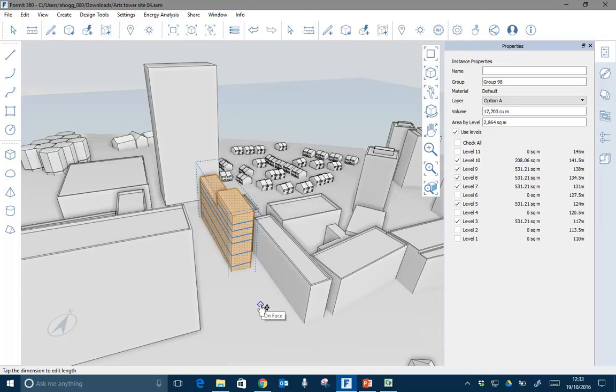And the process in FormIt, you simply go up to this button that says 19.1, which is the energy analysis button, and you would click on Generate Insight. Now, I'm not going to do it because I've already generated an insight for a very slightly different building. But when you generate the insight, it does take anything from maybe 5 minutes through to a few hours to simulate.